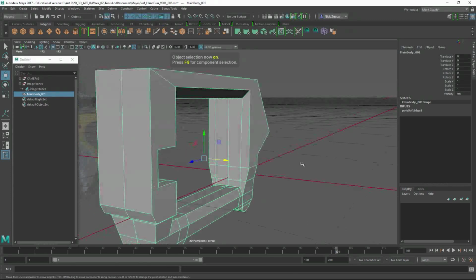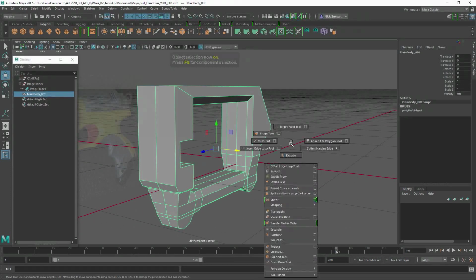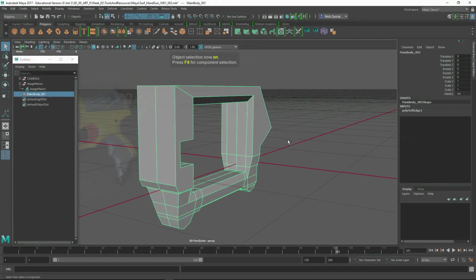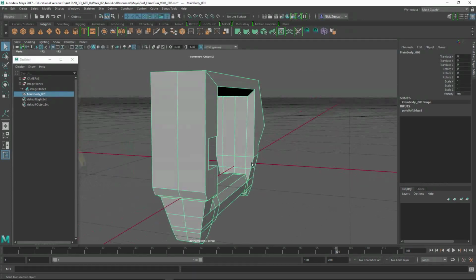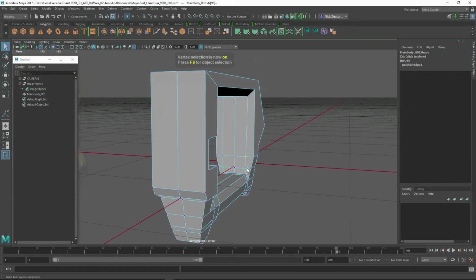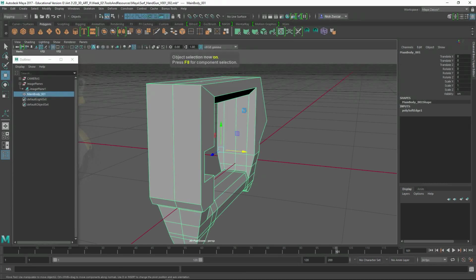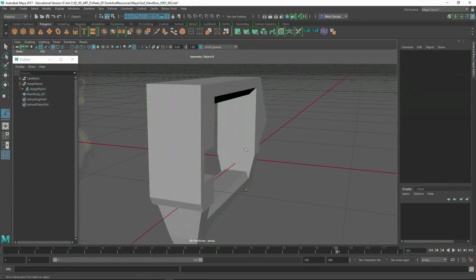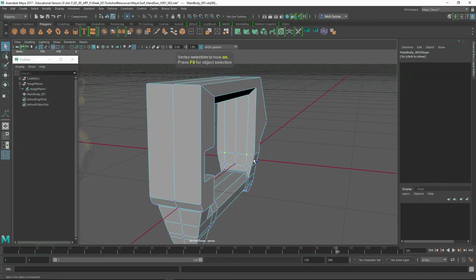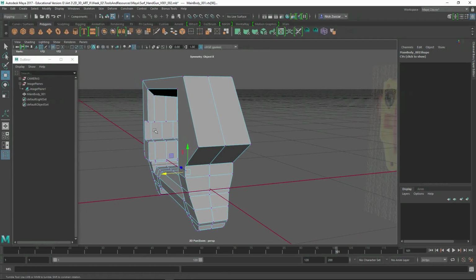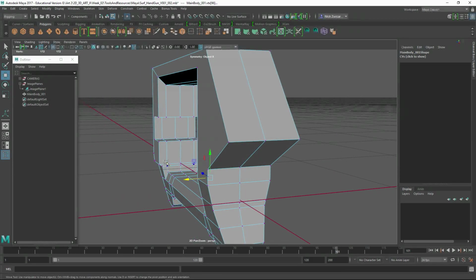Now, what I told you about symmetry before is, let's see here, let's undo that real quick. If you take the model and you Control Shift right click, you can do symmetry. And a lot of these operations that I was doing, you can actually do with symmetry on. It does help if this thing is perfectly symmetrical and mirrored across, right? Then it should be able to find these points and faces, and you should be able to model basically one side of the object, and everything else should follow with it.